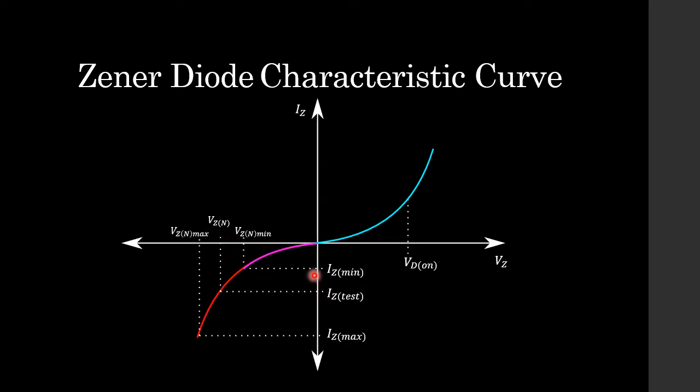However, the difference between the minimum current and the maximum current is going to be a bit larger, because we want our Zener diode to pass quite a bit of saturation current so that it can act as a type of regulator. And we can also note, students, that because this curve in the breakdown region has a slope, that means it's going to have some sort of resistance.